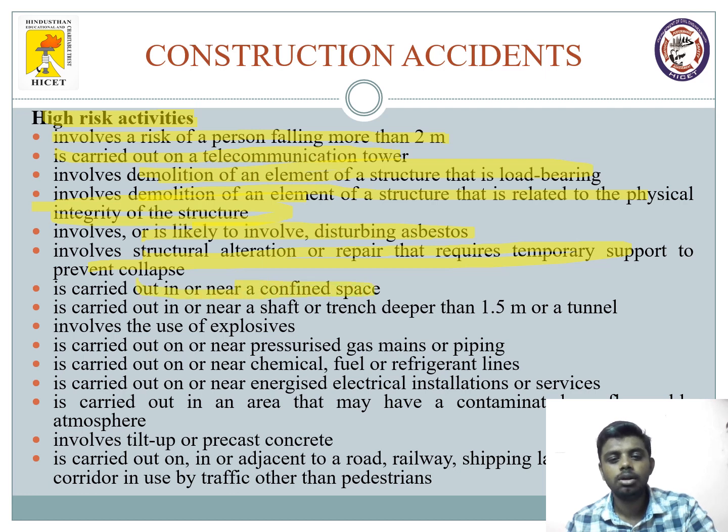If it is carried out in a confined space, if you are working in a confined space, then definitely that is a high risk activity, right? Then if your work is near a shaft or trench deeper than 1.5 meters or a tunnel, this 1.5 meter depth is a very important aspect. You have to take care of your workers. If they are working at a depth of 1.5 meters, then that is a very high risk activity. You have to take care of them.